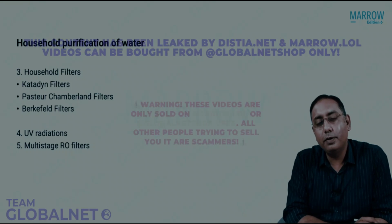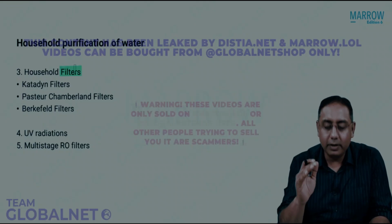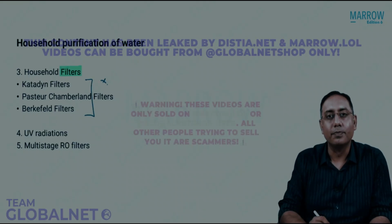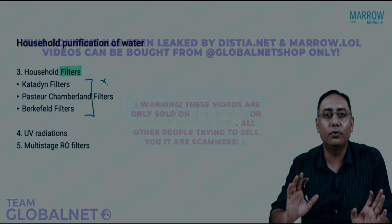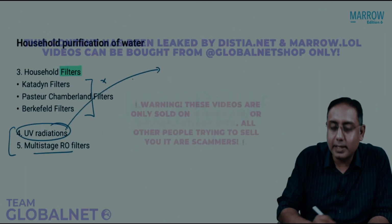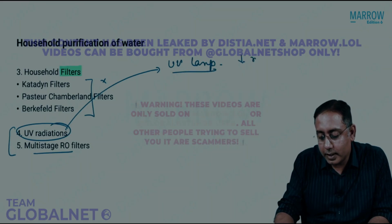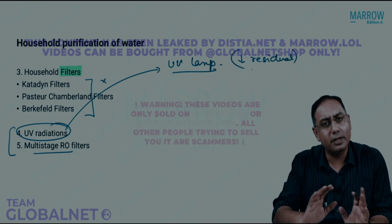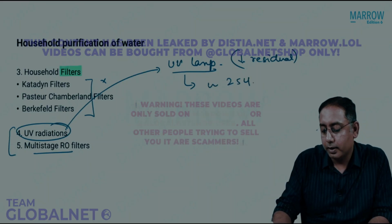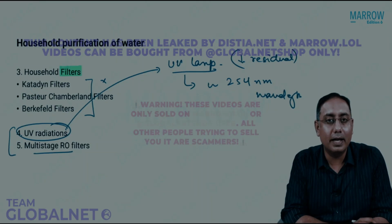Coming next, at the household level, many times some filters can be used. For example, the Katadyn filter, Pasteur-Chamberlain filter, the Berkefeld filters. Please note they are almost obsolete. We are not using them. Now in your home, in my home, in most of the homes, we have UV radiation or multi-stage filters. The problem with UV radiation is again the same thing. There is a UV lamp, but there is almost negligible residual effect. The UV lamp that we use usually has a wavelength of around 254 nanometers. 254 nanometer UV lamps are used in the UV filters.